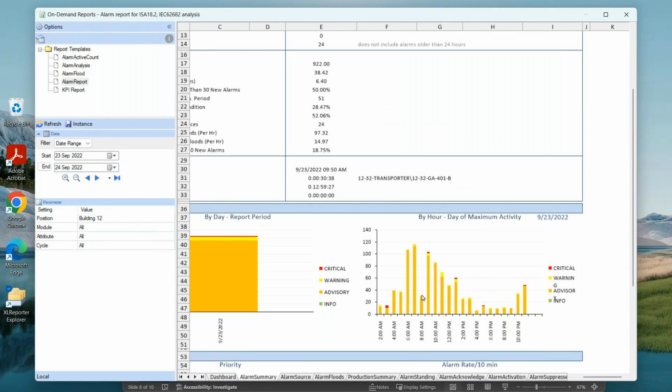On these peak points here, obviously that would resonate with either full production or potentially the potential for lack of coverage. Maybe it's a shift change scenario, and some of these alarms, from being addressed perspective, being acknowledged or not, is falling through the cracks. What this gives you, though, is the ability to target time segments to be more specific in how you investigate why you're getting the alarm volume that you're getting, and how to address it.